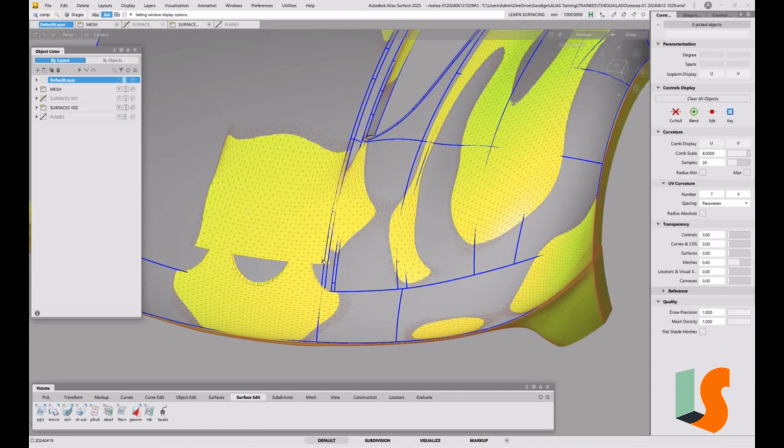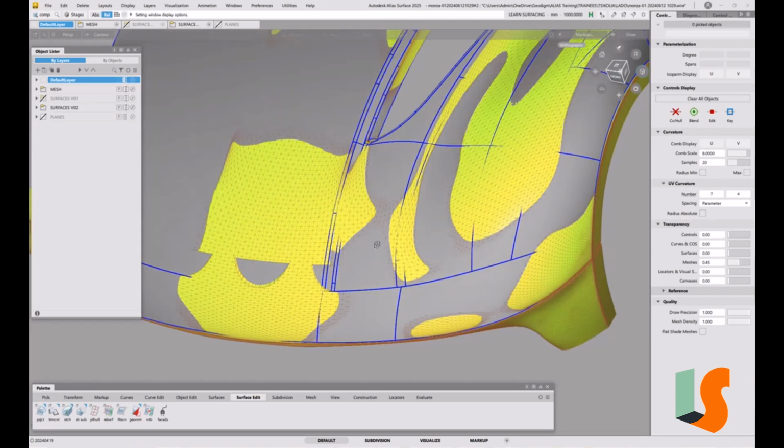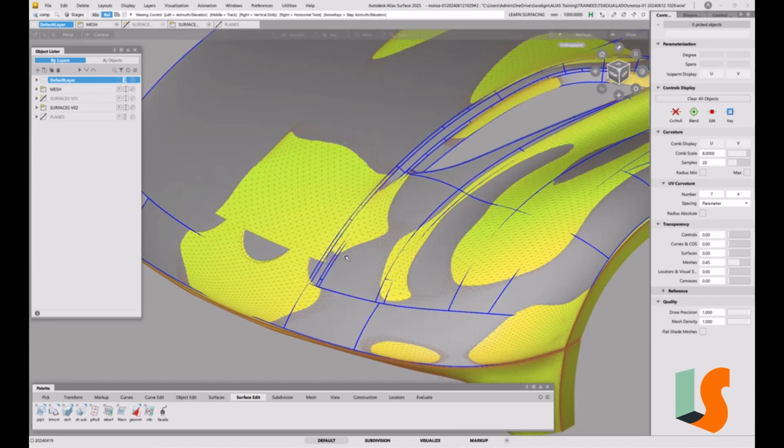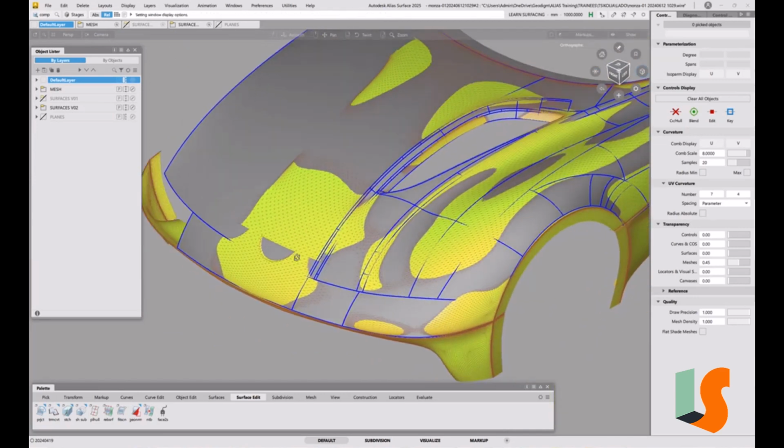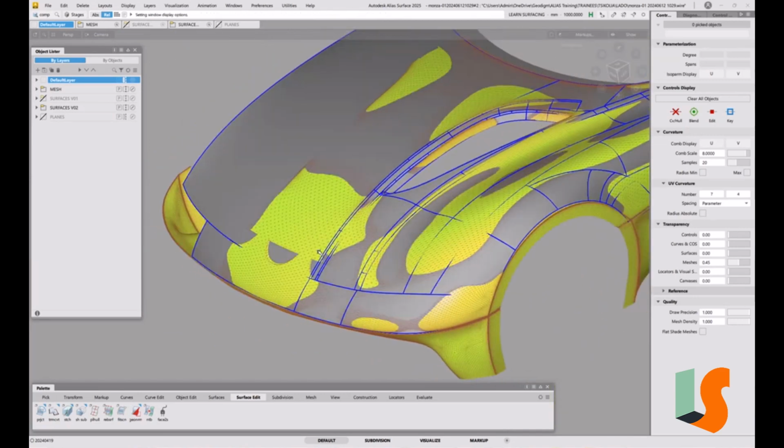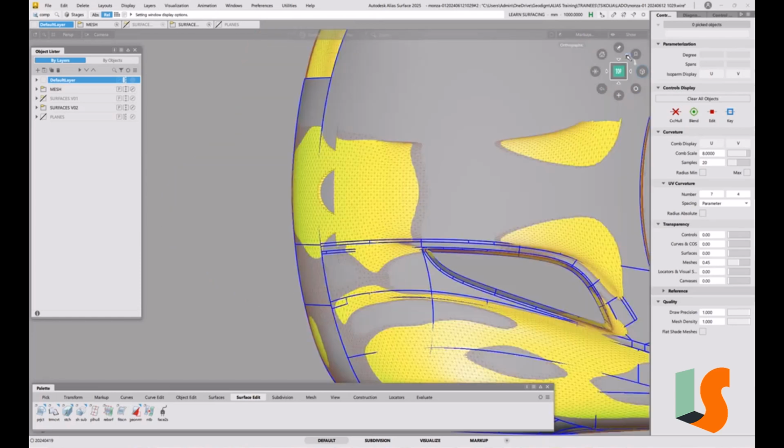And another one where, looking at it now, I think really I should have moved that line up to here, because then we could have washed it out before it hits that edge. Otherwise we might get a wobble in that edge, but hopefully it'll be so small that we won't really notice for this. But another one where, if it was A class, then I would go to the trouble of moving that edge up here. I'm not going to do that because that's a lot of work to do. But yeah, that would be the ideal, because otherwise we're going to have a little bit of a wobble through that area, and we can't avoid that.